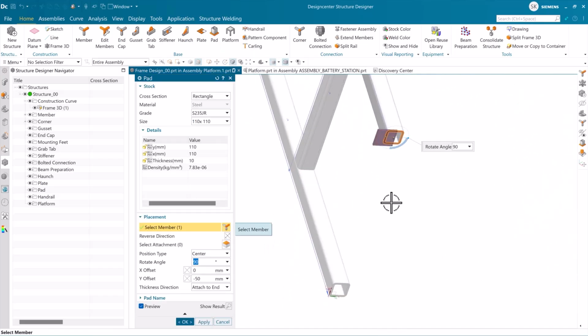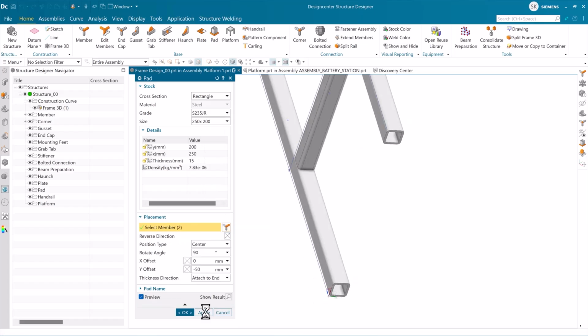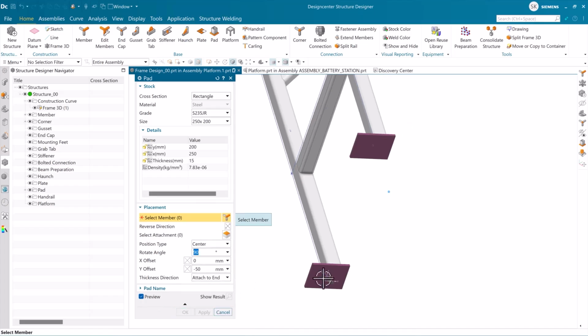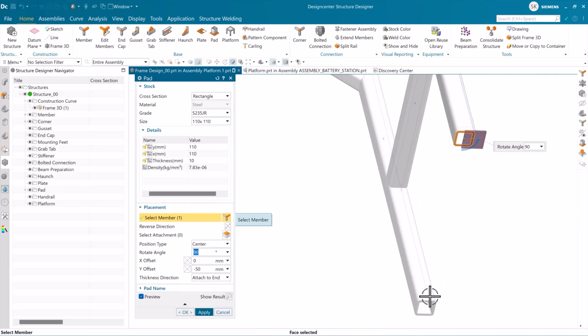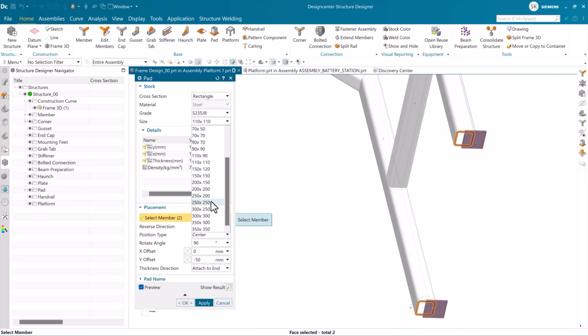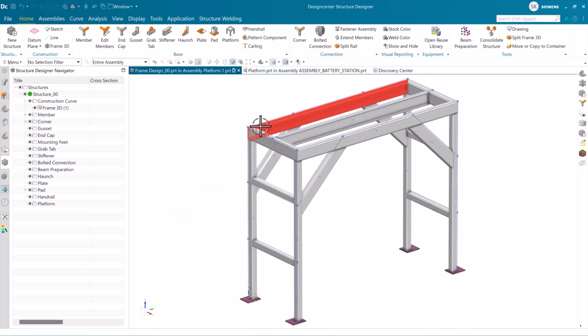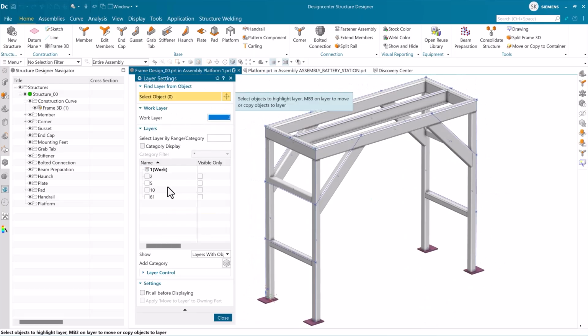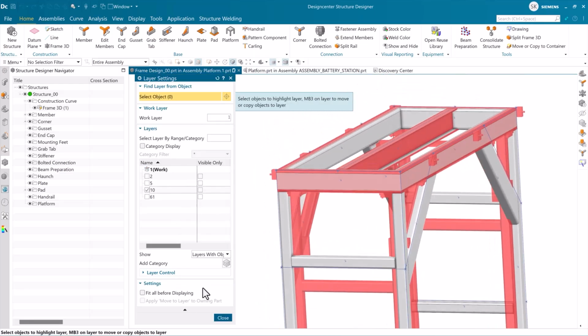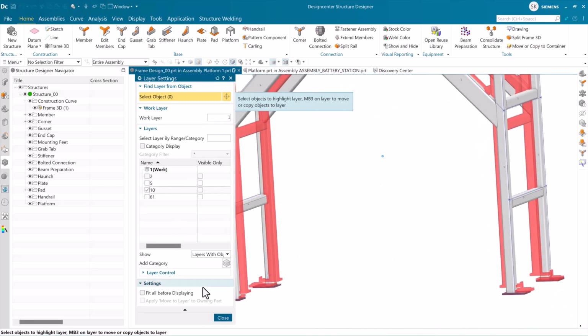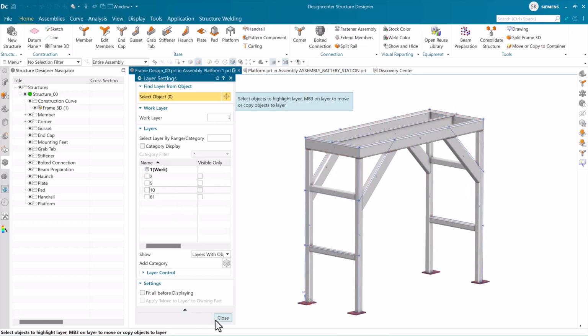Selecting different width and length will provide space for weldments of the pads and mounting space for these pads on the floor. Once we see all the frame members are created and properly trimmed, let's do a visual review of the newly created frame members in comparison to the scanned data that is in a different layer. Once we are satisfied that our newly created frame design matches the scanned data, we will now develop manufacturing options